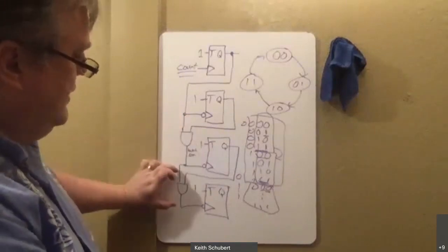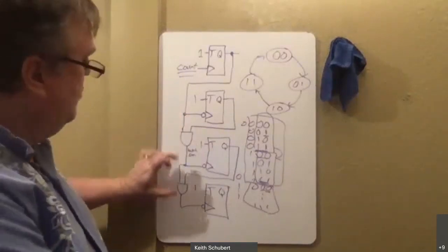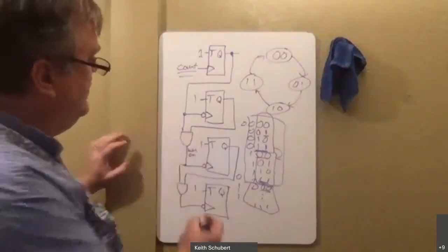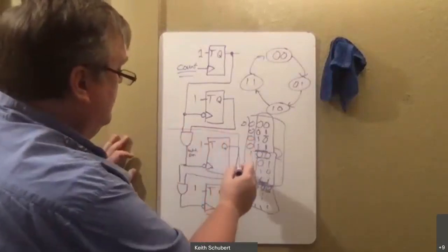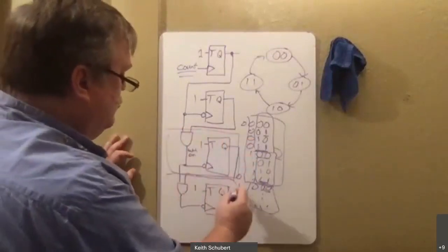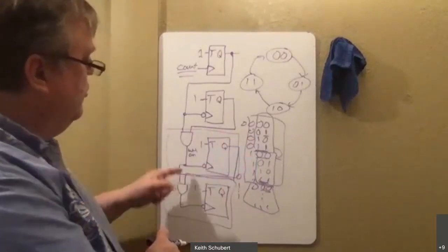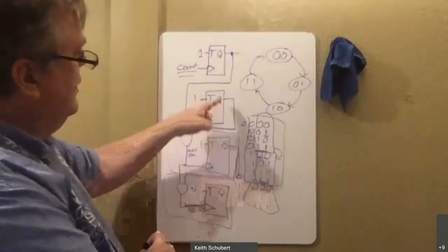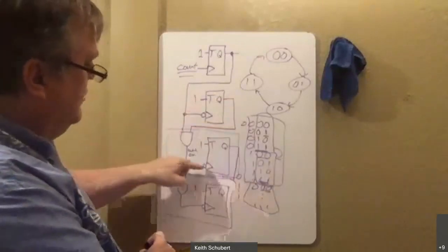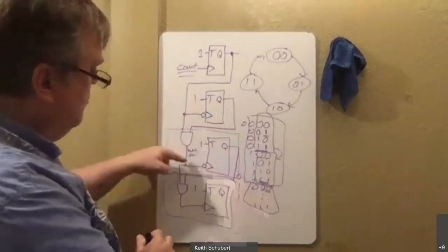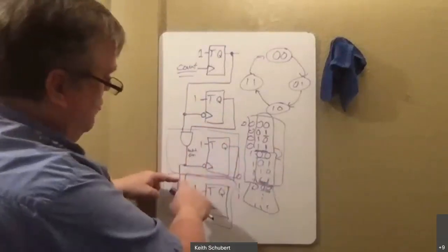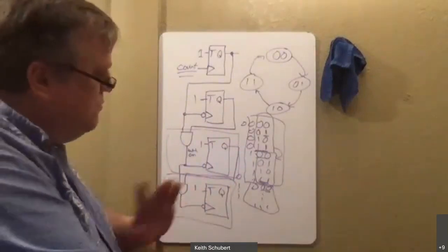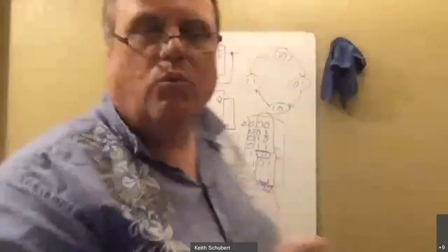So you can notice, right, this is the nice thing about the ripple addition. Just like with a ripple adder, the ripple counter has a nice simple block here that you can just repeat over and over and over again. It just takes the previous clock's input and the Q output, ANDs them together, and that becomes the clock input. Previous clock's input and the Q goes into an AND gate, next clock. You can add that for as many bits as you want, and it will work.